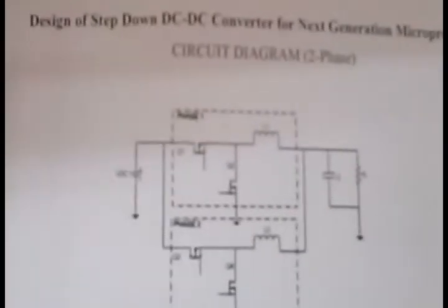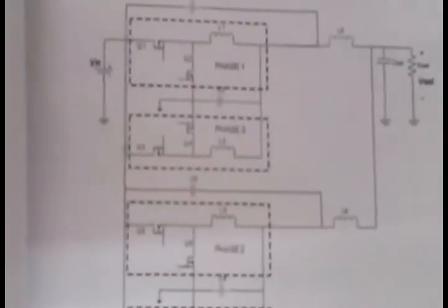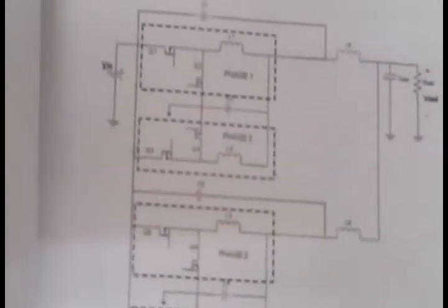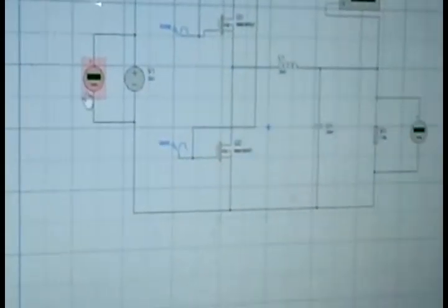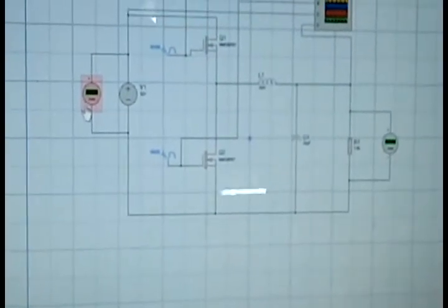The first 2 MOSFETs form a synchronous buck converter, and each MOSFET operates synchronously. In each phase, the first MOSFET operates from the input supply, and the second MOSFET supplies the charging and discharging of the capacitor. We use the inductor to reduce the harmonics and ripples of the output voltage, because the DC step output has harmonics.